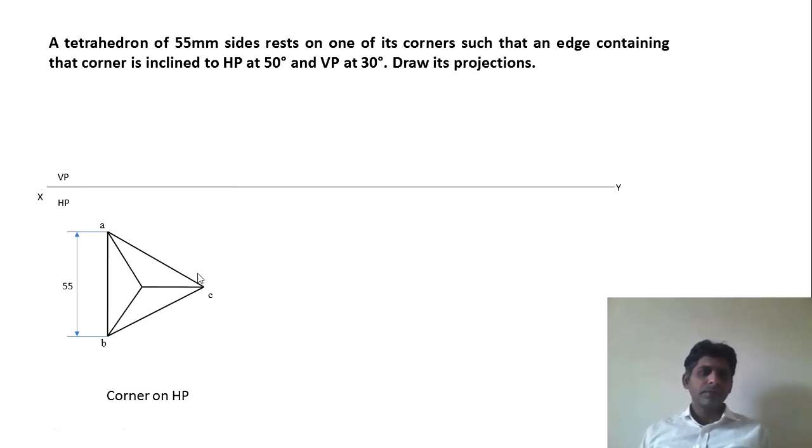Once you get the point, this point will be O1 and O2 will be in brackets because that is on the base. So you have to join all of these slant edges. Next you have to take the projectors. Notice here that the length of the axis is not given, and it will not be given for a tetrahedron. So how to construct this?